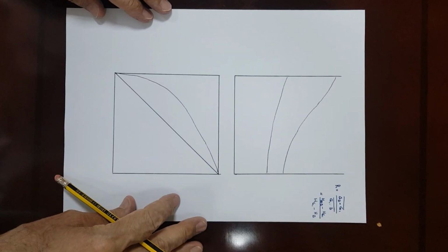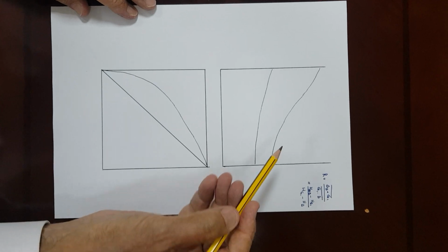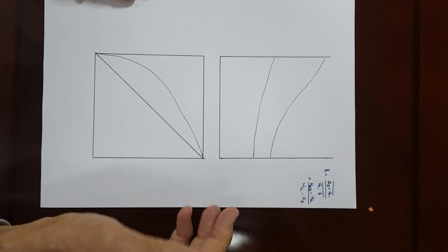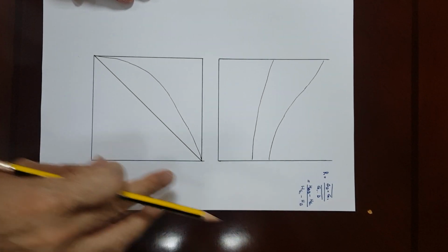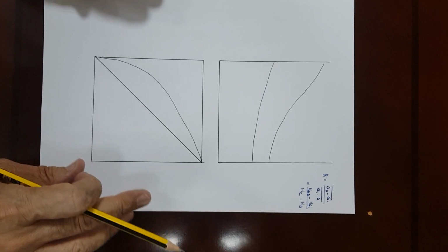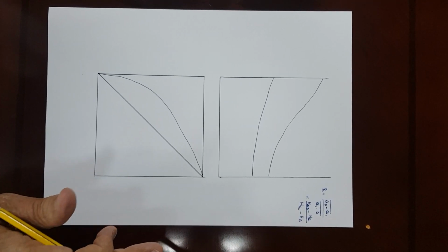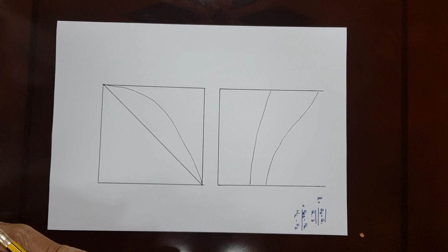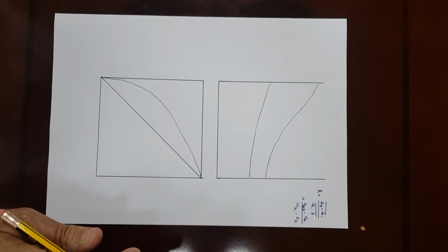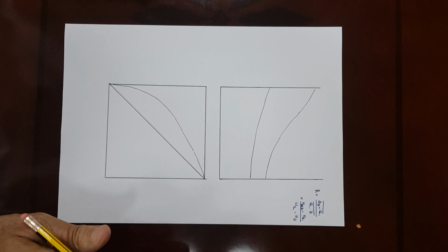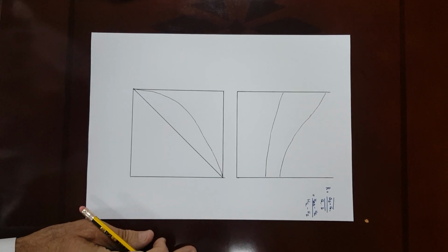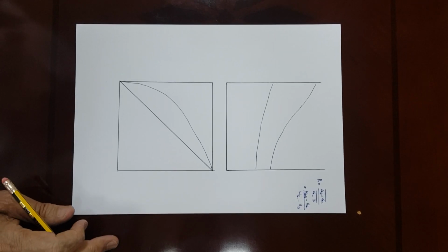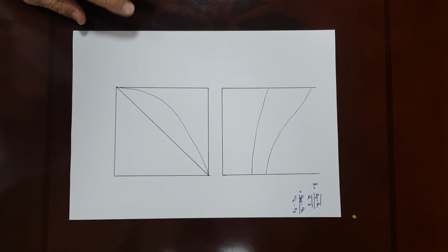So to start with, this is the enthalpy diagram versus the y versus x concentration diagram. This is the vapor equilibrium enthalpy, and this is against the liquid enthalpy diagram. Initially, we normally specify the reflux ratio and the distillate concentration. In terms of flow rates, normally we specify the distillate's flow rate, or alternatively we can specify the feed's flow rate.